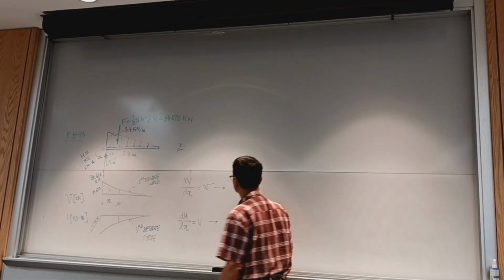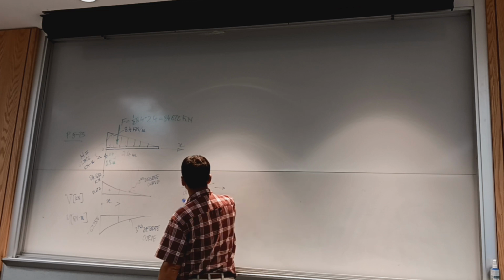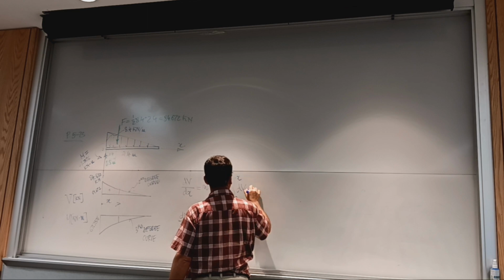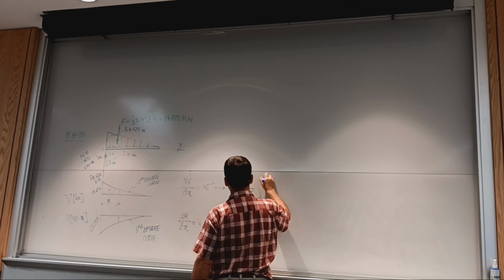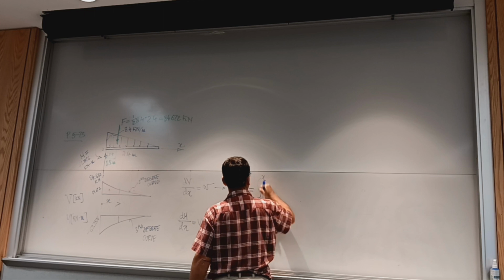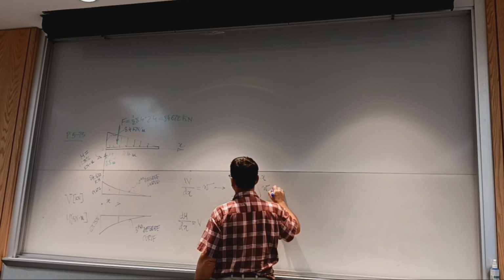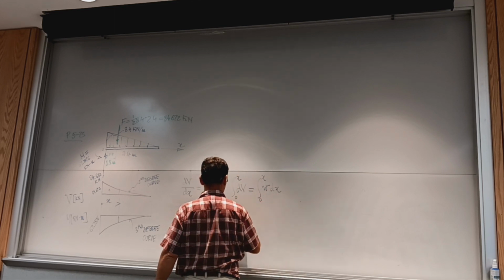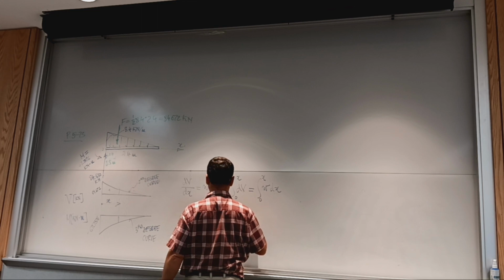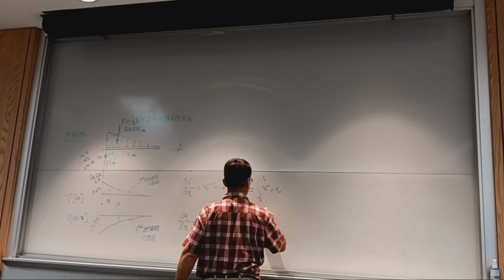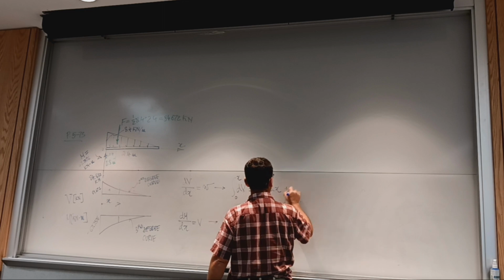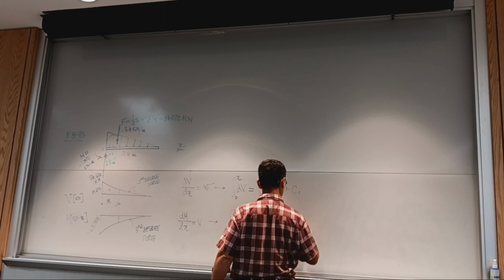All right, so we're going to integrate. dV going from 0 to x equals the integral from 0 to x of the distributed force, dx. In this one, dM equals the integral from 0 to x of V dx, and I have to have constants of integration, constant 1 and constant 2.